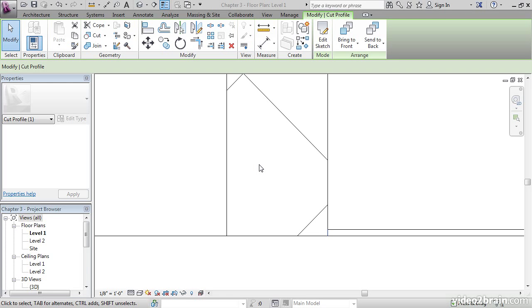All right, I think that does us. This is a good trick to know. Many times I'm surprised how many people don't know how to pick the wall join button or split a cut profile, then find the intersection to join. You've got a little trick in your bag.